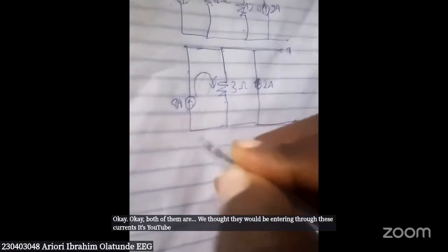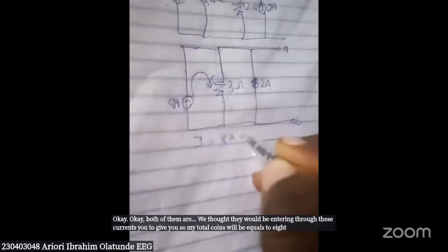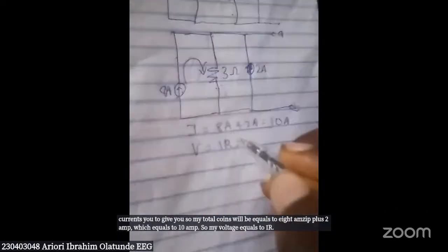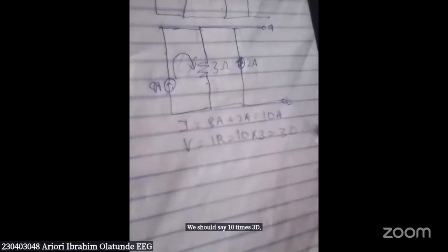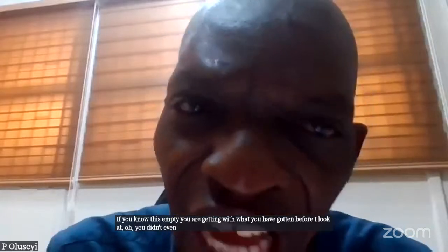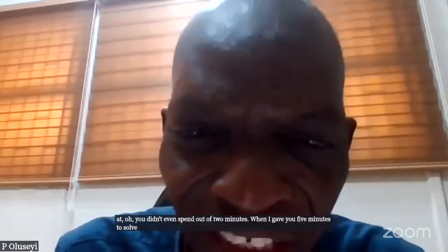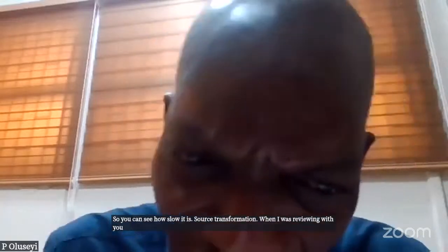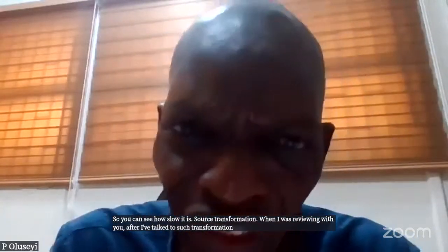So my total current will be equal to 8 ampere plus 2 ampere, which equals 10 ampere. So my voltage equals IR, which is 10 times 3, which equals 30 volts. Is it not the same thing you got before? It is, sir. And look at what you did. You didn't even spend up to 2 minutes, and I gave you 5 minutes to solve that problem initially. So you can see how short it is. That's why I kept on repeating source transformation. When I was reviewing with you, I said I've taught you source transformation. So what is your resistor now?